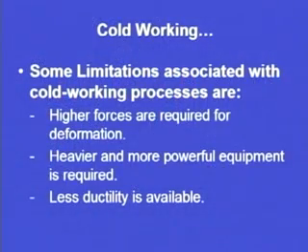So, we have seen that there are certain advantages of cold working operations over the hot working operations, but it is only one side of the coin. There are certain limitations also with cold working operations. So, what are these limitations? Higher forces are required for deformation. Whenever the metal is at an elevated temperature, its ductility increases and its strength decreases. Reduced strength and increased ductility help to form the metal in the desired shape. But in case of cold working, there is no elevated temperature. So, at room temperature, higher forces are required for deformation.